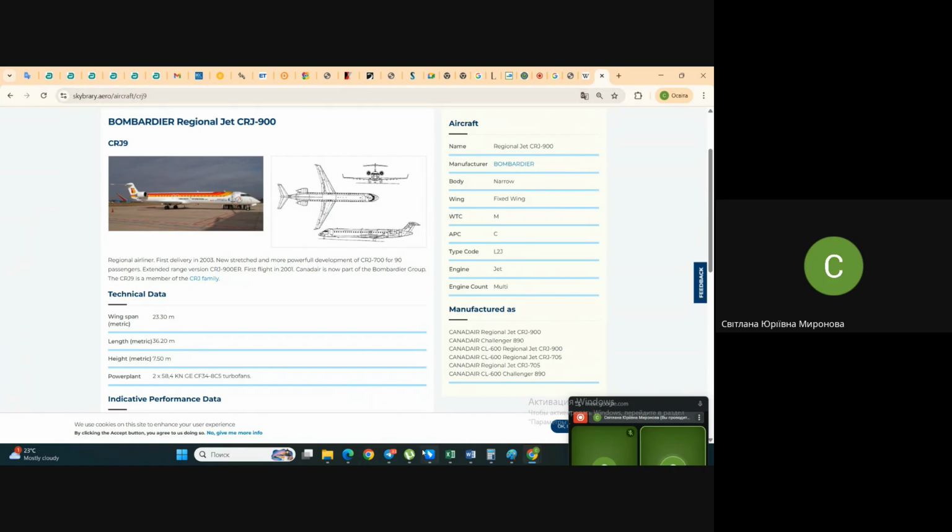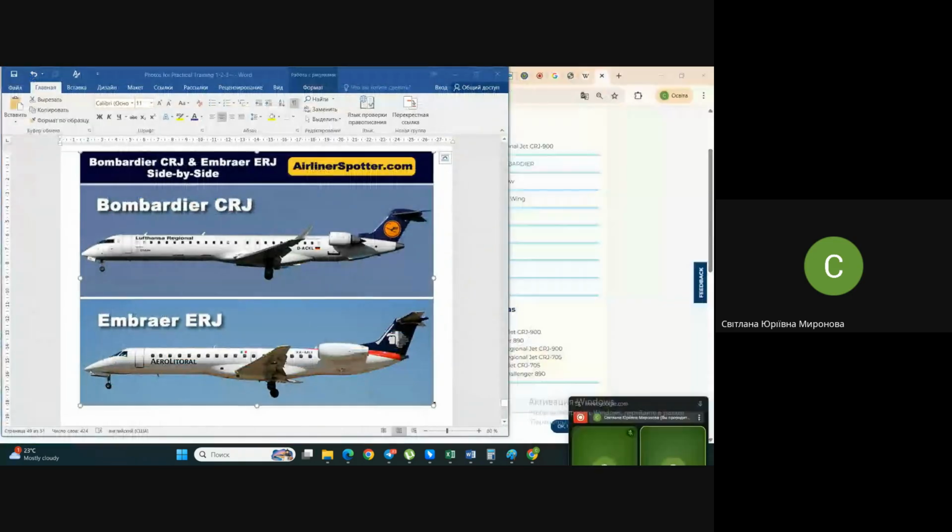But the general idea is turbojet for higher speed, turbofans for less speed, but turbofans help you save fuel. Turbojet is a more greedy engine. It takes more fuel. It has a higher fuel consumption ratio. And the turbofan is the more economic variant. But of course, this one is more difficult to place in the geometry of the airplane. And in general, you see similar purposes,